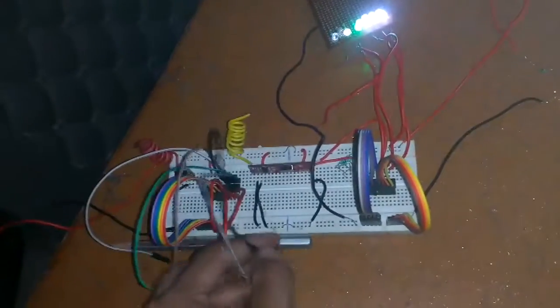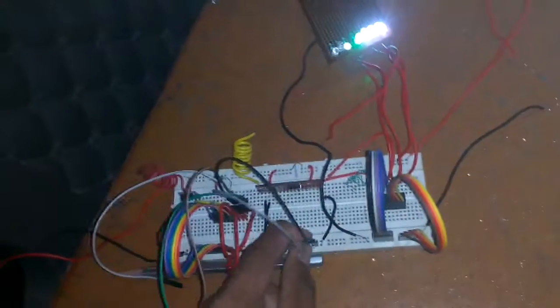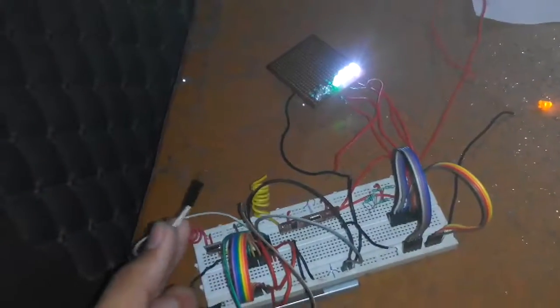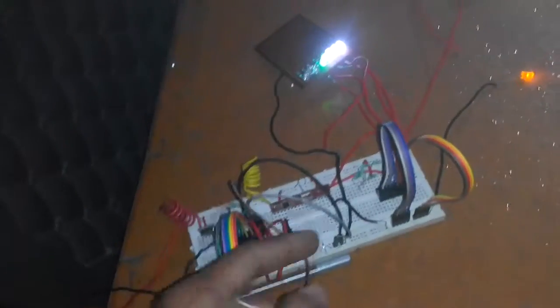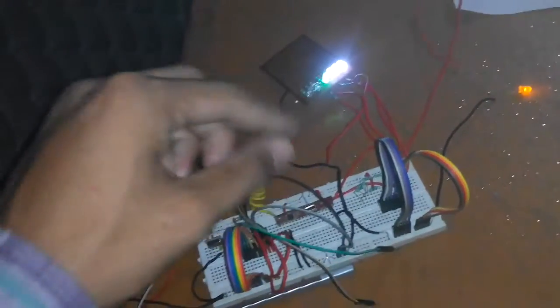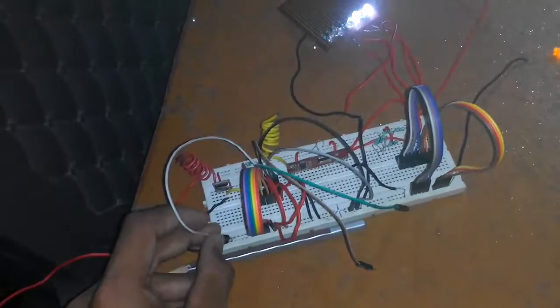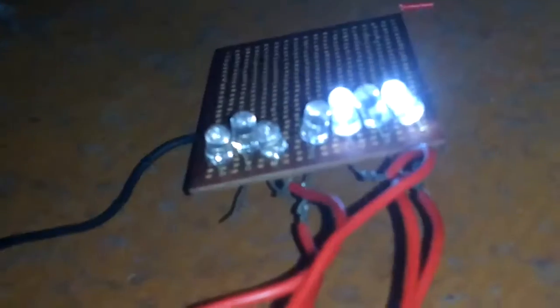Now I'm going to ground some data, or send some data. I have grounded two jumper wires for that purpose. Now I'm going to take this pin 14, the transmission enable pin. As I grounded two pins and left two out, two LEDs should be off. Now I'm going to touch, and there it is, two LEDs are off. As you can see on the other side of these LEDs.